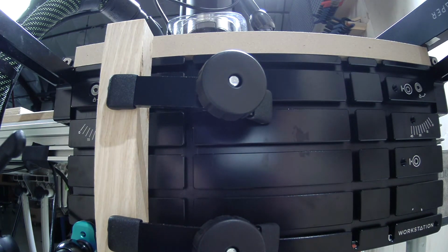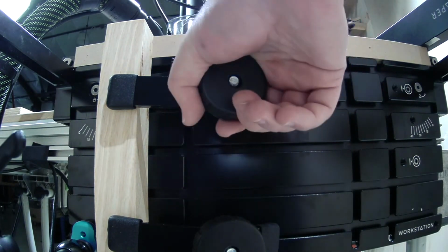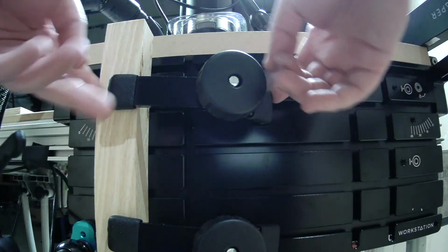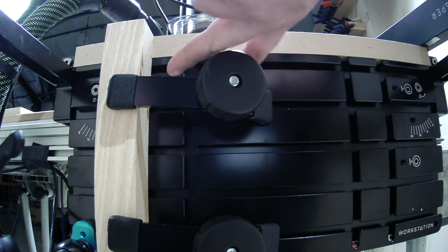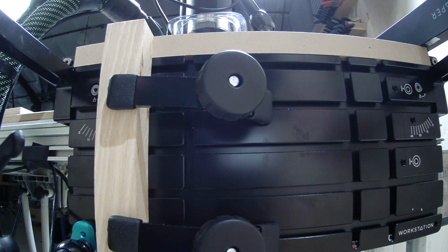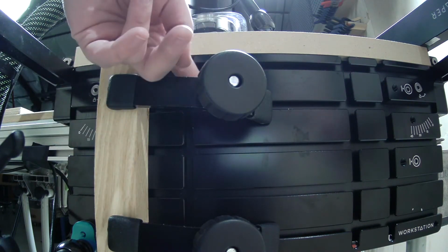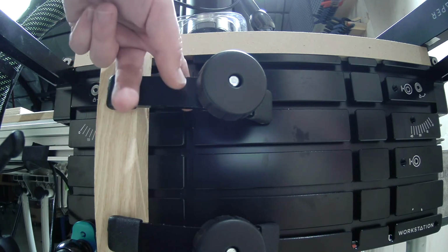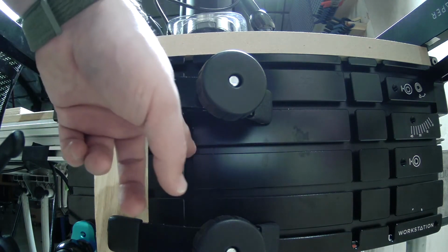The basic idea here is these are just standard T-slot cantilever clamps. 2 of these ship with Workstation, so they're in that toolkit, and you can actually use them in both directions. I think in this particular case, I am using them one way, and I would probably flip them around, but you just want to make sure that where the T-track bolt lines up with a track in the clamping face of Workstation. It's really important, and it's easy.